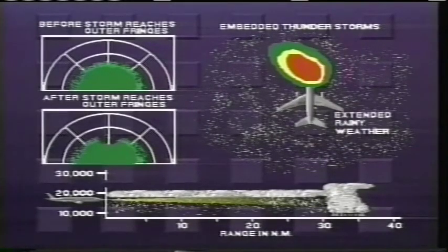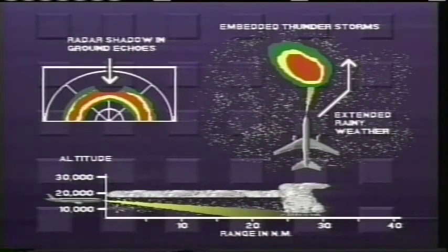If, on the other hand, you adjust the radar tilt to direct the beam toward the ground, you will see this radar presentation. Now, when you approach the embedded thunderstorm, you will see the ground returns become shadowed and immediately make the decision to fly away from that area. Under these weather conditions, always fly toward the displayed ground returns.